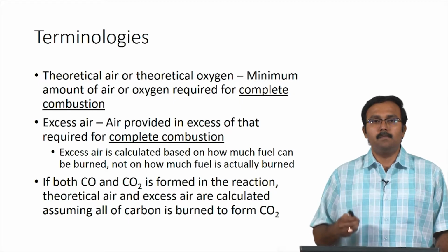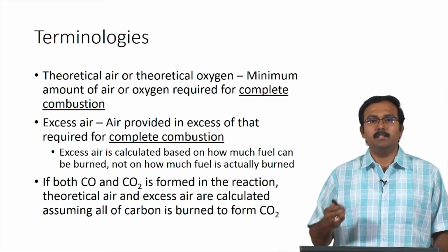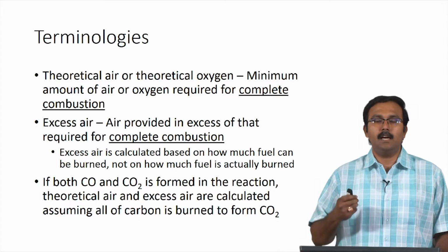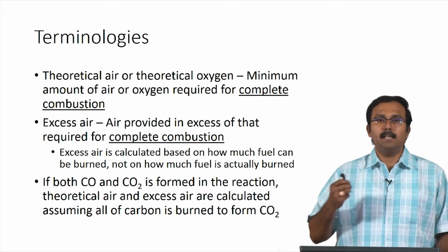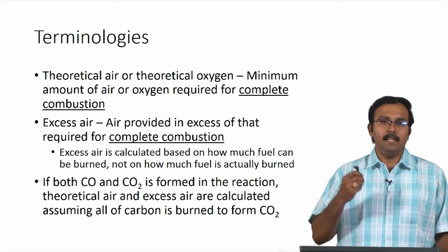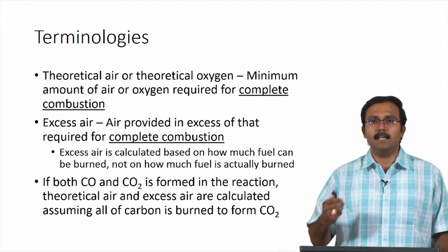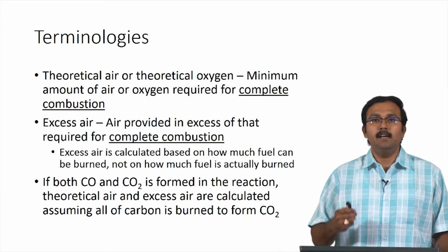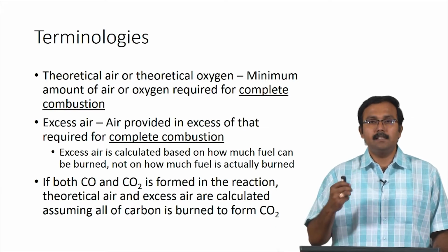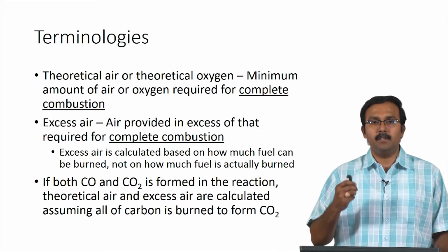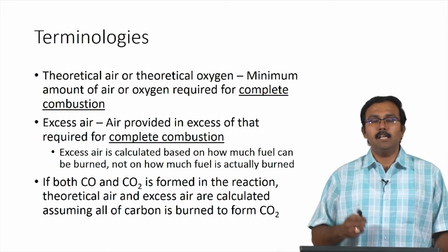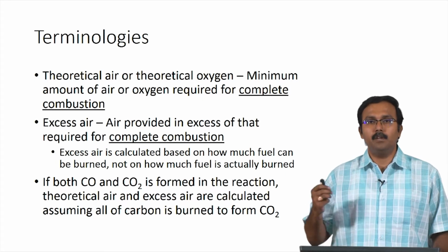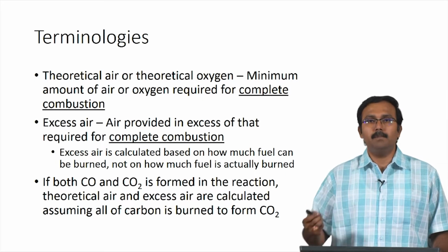These two terms, theoretical air or oxygen and excess air, are actually calculated based on the assumption that complete combustion happens. This means even if carbon monoxide and carbon dioxide are both formed in a reaction, in reality, however, we should calculate these theoretical terms of theoretical air and excess air based on reactions happening in a way that all of carbon is converted to carbon dioxide, which is what complete combustion is.